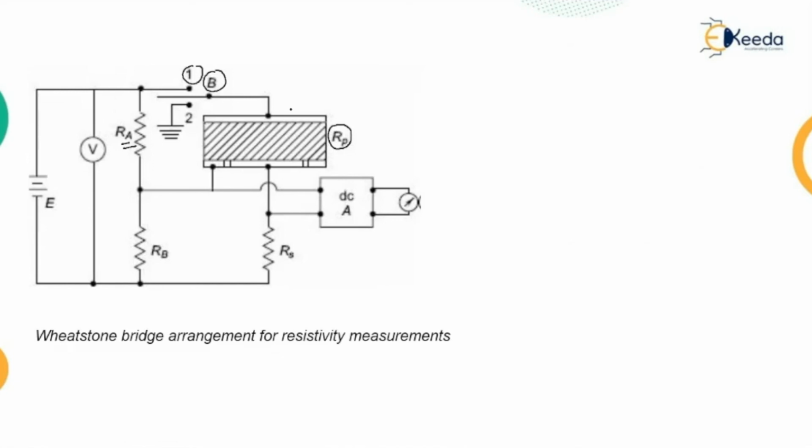And as already said, there are guarded, unguarded, and guard terminals. So we have these 3 terminals, which are already shown in the previous diagram: the unguarded electrode, the first one; the guard electrode, the lower one; and the side one is the guarded electrode. These are shown here. And we have this balancing resistance RA that balances, and therefore it is called a Wheatstone bridge.